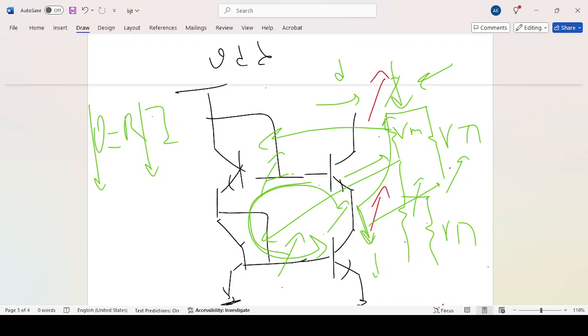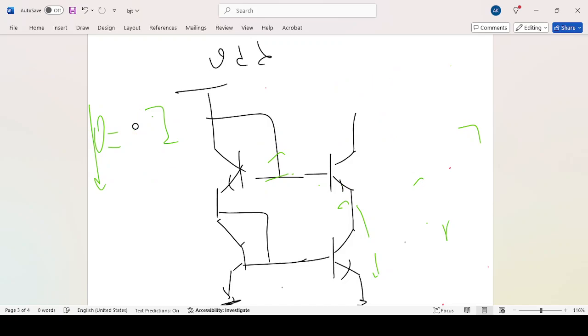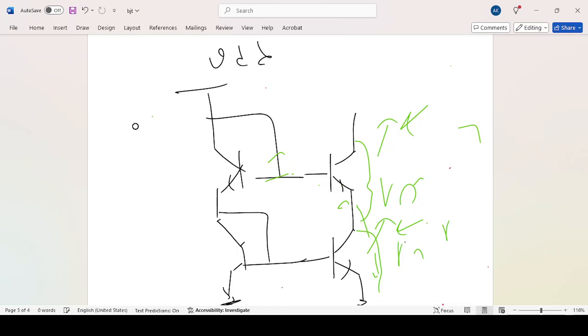Or another way to look at it is the way that I told you about, and mentioned earlier, is you just draw RO. You know this one is increasing, so this one also has RO. So when the voltage here is increasing, this one is increasing too, so you have a current that is not in favor of the current of the voltage source that you added here to measure the output resistance.